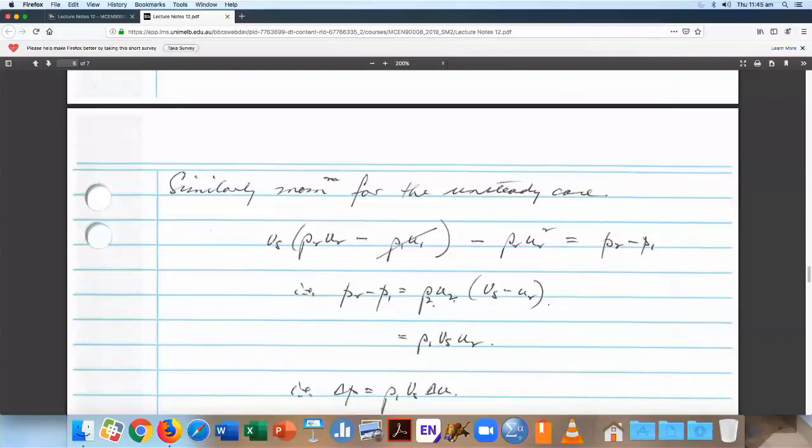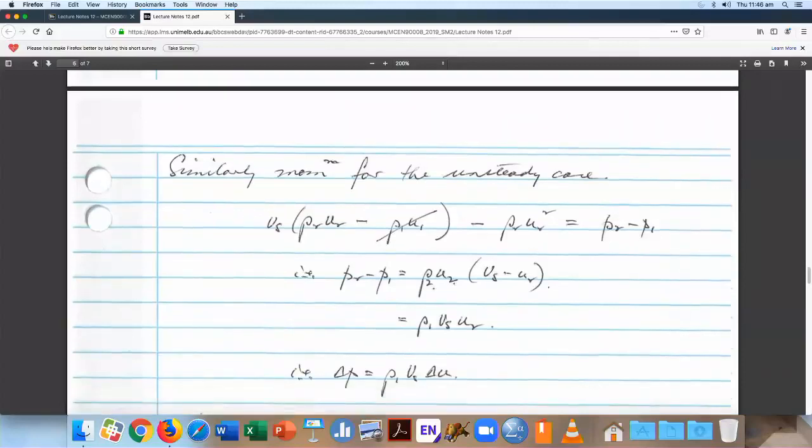And it's equal to rho 1, which is not necessarily small, times us, which is the speed of sound, roughly speaking, which is not small, but it's times delta U. So delta U is very small if delta P is very small. So if I have a weak shock, the velocity behind the shock is very tiny. So that's an important idea, and we're going to work that out.